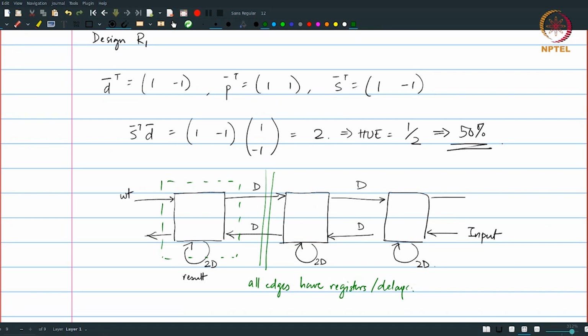With this, I'm going to conclude the discussion of systolic array architectures. As you can see, it is just a very high level overview of the process by which we can take a dependence graph and map it onto a given architecture. The main things that I want you to focus on as far as this particular coverage of the topic is concerned is that we are assuming that there is some way by which you can already create a dependence graph, and the only thing that we are really looking at is what are the properties to be satisfied by the projection and scheduling vectors, and how do we go about systematically taking a set of values for projection and scheduling vectors and converting them into a hardware architecture. More importantly, we also looked at the specific example of the FIR filter in order to see how that gets converted, how we can take a single dependence graph and convert it into different architectures for an FIR filter, each of which has a different set of properties.